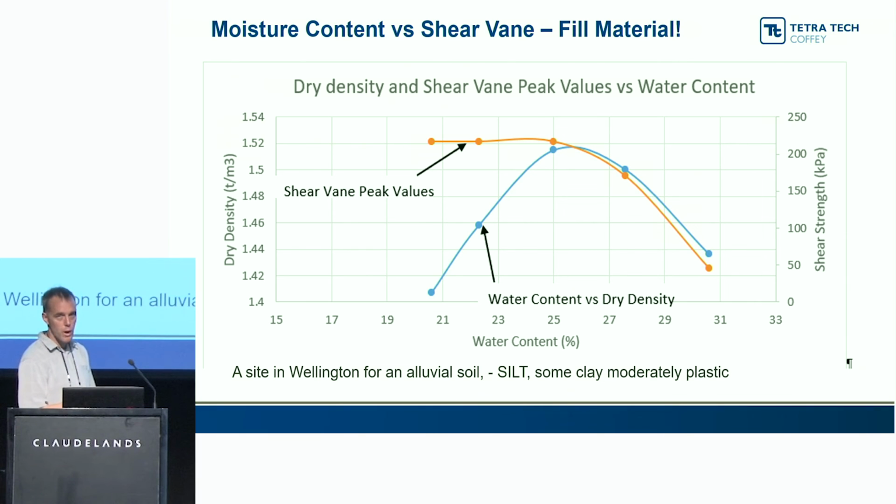This side is quite good though. This is great. You turn up to the site, and if you saw this, you test it with a DCP or shear vane, you'd get a bad result. Happy days, you tell the guys they've done a bad job. This side out here is actually a bit misleading.